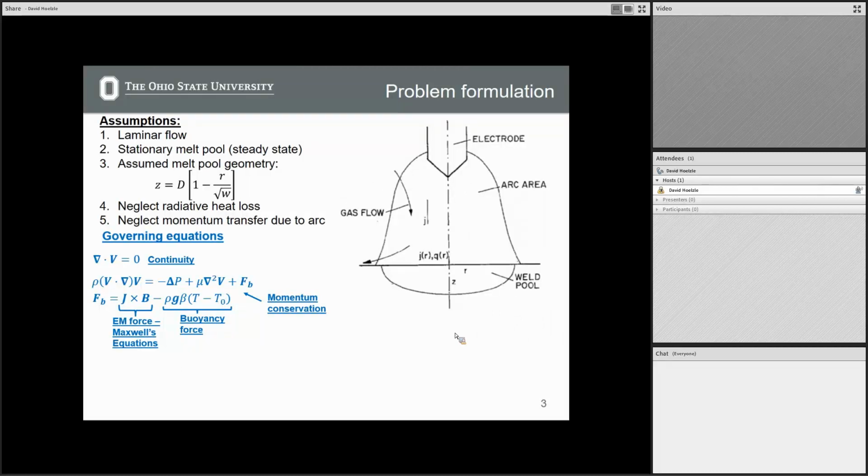So right off the bat, this is already an extraordinarily complex multi-physics nonlinear model, and we haven't even gotten to the heat transfer yet, which is specified. So we have our temperature coupling into our momentum, coupling into our mass conservation, coupling into our electromagnetism. Models of this order of complexity are one of the reasons why, when Professor Helsing throws up these simulations, they say it takes 100,000 CPU hours to run a single weld track. Models of this complexity are why, because you need this kind of extreme multi-physics to adequately capture the processes.